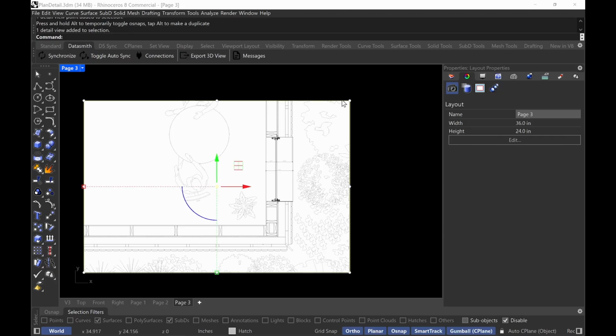So if I click on my detail, you see right here, it's giving me 1 inch equals basically, this is the scale factor. You can type it in the regular scale, so don't forget that. Like you can type in inches, 3 inches, feet, 1. But don't type in the actual symbol, just type in 3 and 1, okay? Don't type in the inch symbol or the foot symbol. Just type in 3, 1, and then it'll automatically convert it for you, okay? So that's set. Now, the other things I want to talk to you about, which is very important, are the line weights, the line types, the dimension styles, and how I'm importing hatches, okay?